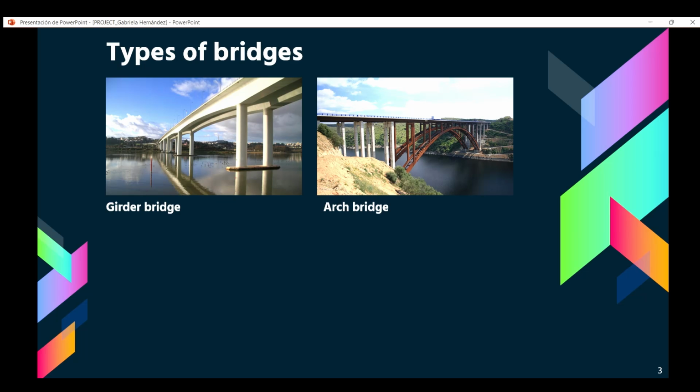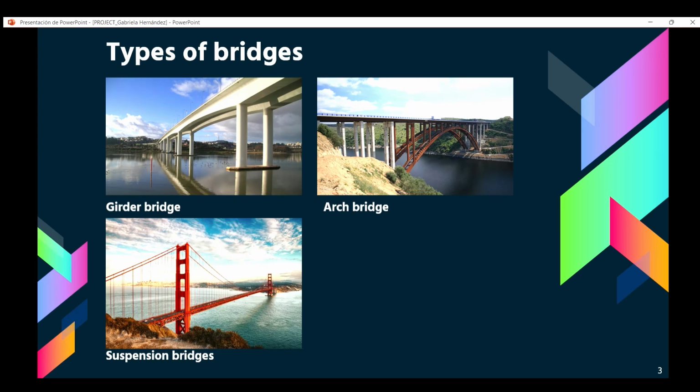Suspension bridges. These consist of a deck over which one travels, which hangs by means of a large number of stay cables from two large cables that form catenary cables that are anchored at the ends of the bridge and supported on large concrete or steel towers.